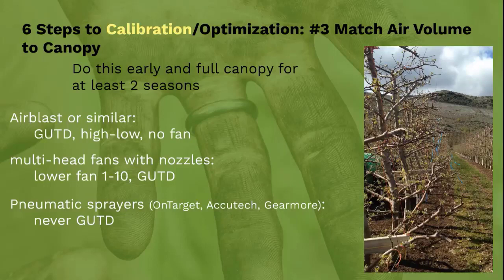If you have too much air and you have an axial fan sprayer or a multi-headed sprayer, such as a Quantum Mist or something with the Sardi head fan with exchangeable nozzles, then you can easily try to gear up and throttle down. So what this means is that you increase your gear, which makes you go faster, but you throttle down. Depending on what type of tractor you own, the display will go from 2400 to 1900 RPM or like 540 to 540E.